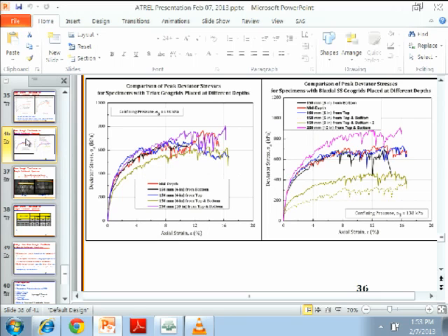A couple of different mechanisms happen. Ballast aggregate materials crush unbelievably, and that never happens in highway base courses. With repeated load application, the geogrid strengthens and arrests the movement of ballast so that the ballast doesn't reorient and break the flat elongated particles, and everything stays in place. That is exactly what geogrid contributes in the long run to cut down the permanent deformation.